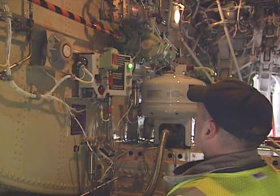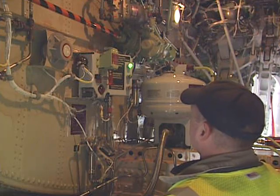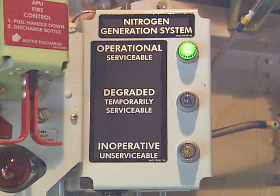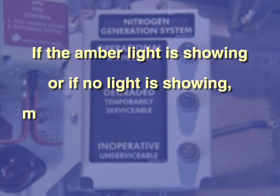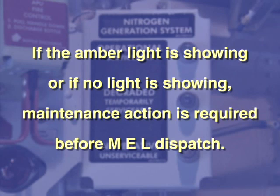NGS status shows on the operability indicator in the right wheel well. If the green or upper light shows, there are no faults detected and the system is fully operable. If the blue or middle light shows, the system is operating in degraded performance mode, but no maintenance action is required for MEL dispatch. If the amber or lower light shows, there is an NGS system fault. And if there is no light showing, the NGS system is inoperative. Note that if the amber light is showing, or if no light is showing, maintenance action to deactivate the NGS system is required before MEL dispatch.